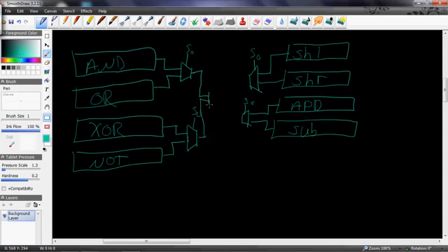So then the next layer was a mux with S1 as the driving signal, and they all did that. All the first 2 muxes funneled into S1 mux, and these both funneled into my S2 mux. So this looks kind of messy, but oh well. And the output came from the final S2 mux.